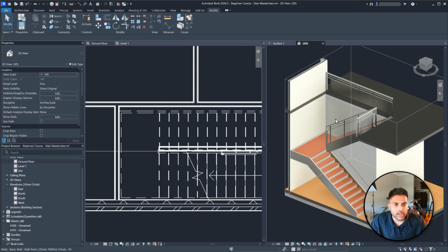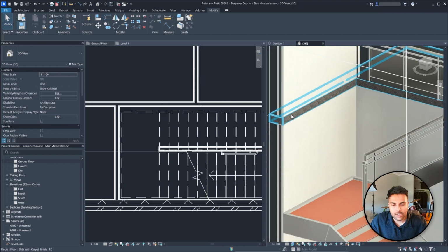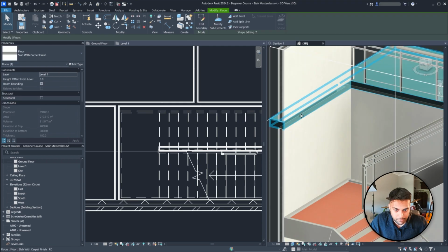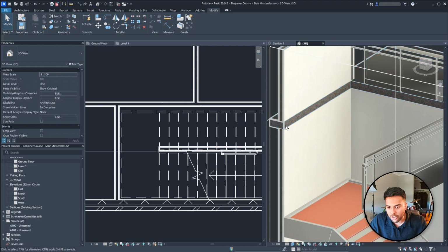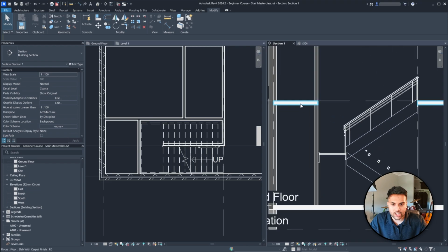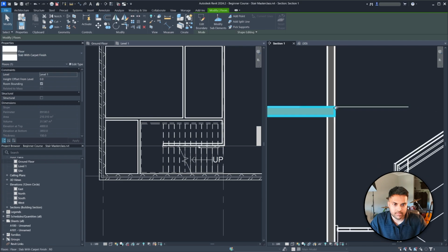One additional thing, you might want to clean this up in terms of the walls, because you've placed your walls and you place your floors. When you have a staircase, you have a cutting or an opening in that area. What ends up happening is, most of the time, since you place walls on the top and the bottom, you have this, which is just the floor slab, which you can see, which is not ideal, right? So maybe if we go to our section view, we can see that issue. You have this floor slab which is actually sitting flush with the walls, and we don't want that. We want the walls to be fully white. We don't want to see any slab when we're going upstairs.